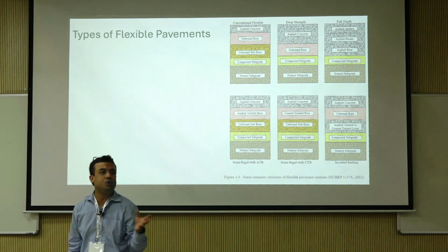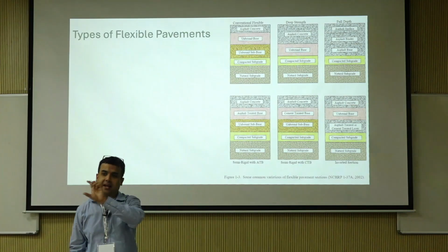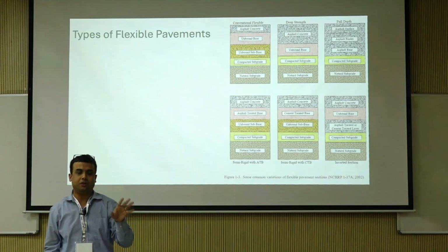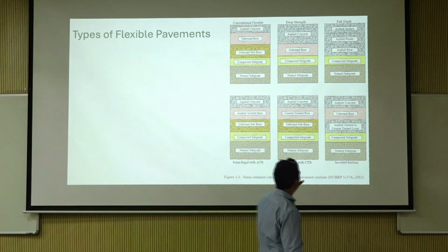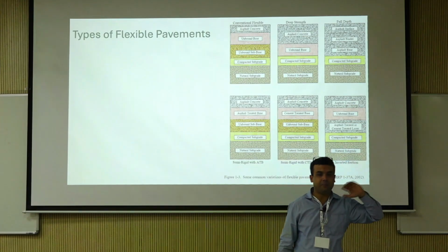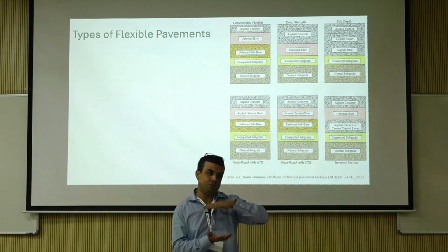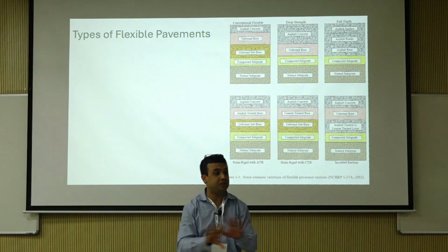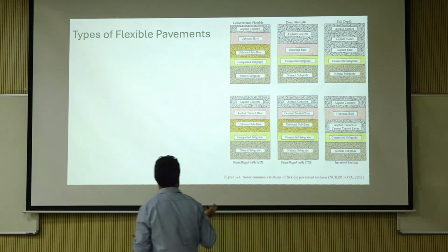So all you need to do for a perpetual pavement is some milling and some surface maintenance, and it will stay, right? So the point is, in a perpetual pavement you never get to the subgrade layer or the base layer, because that defeats the purpose. So there you have to have a proper design before you start building. A lot of times you do a lime stabilization of the subgrade, after which you do a full depth asphalt and stuff like that.